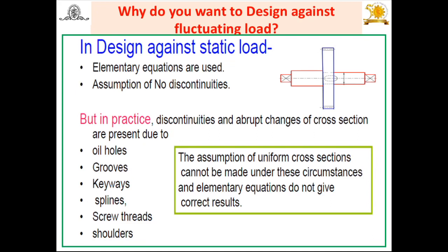While designing components against static load, for the area we assume a uniform cross section. But in actual practice, because of these discontinuities or abrupt changes in cross section or geometry, the area changes. In another way, the elementary equation doesn't give the correct results. This is one of the reasons.